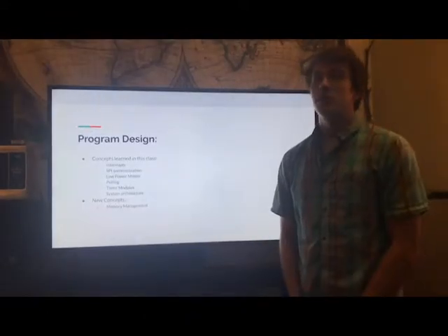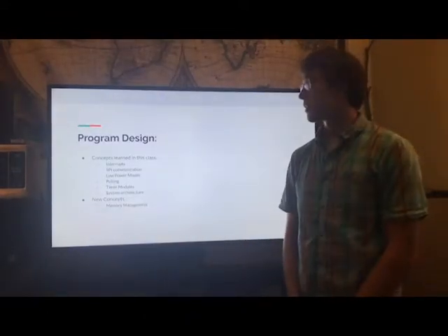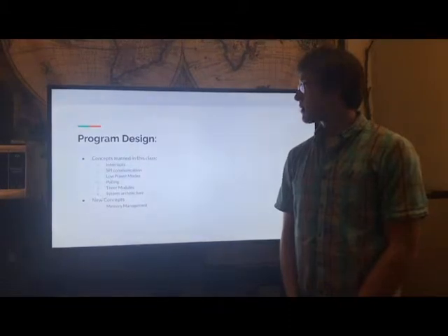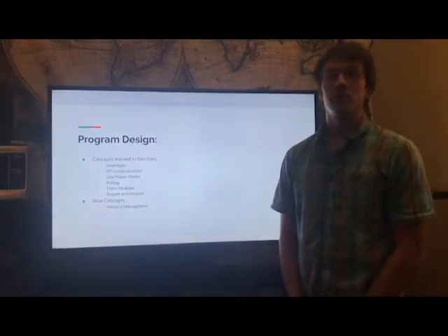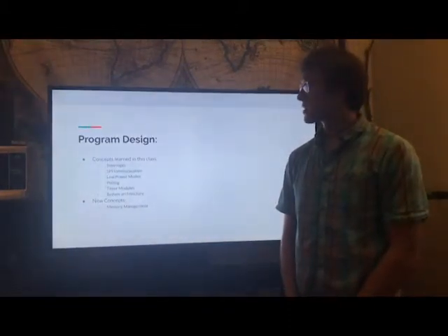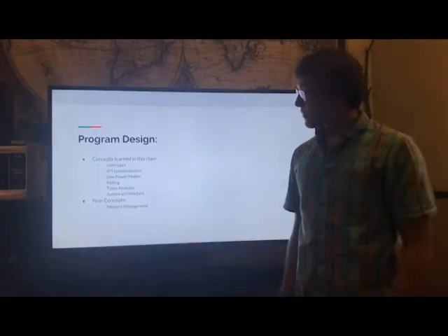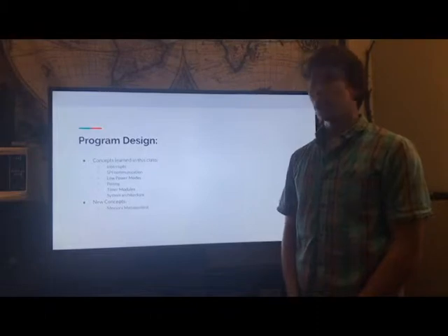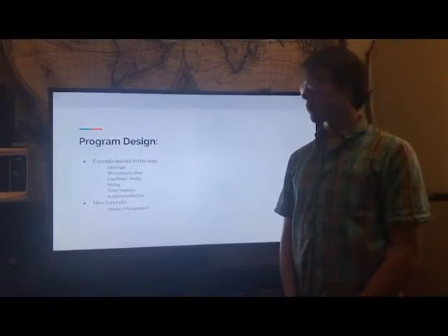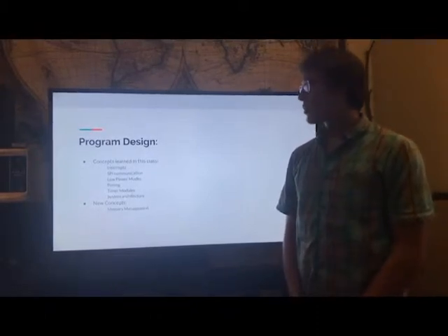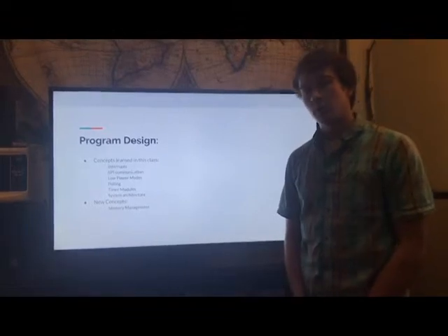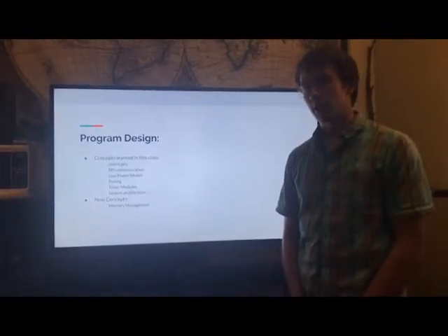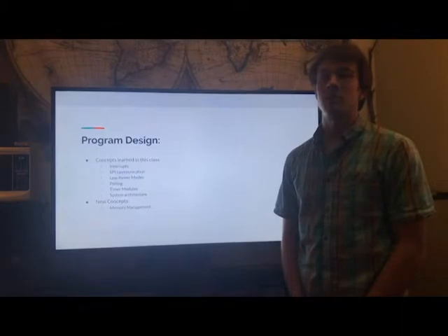This project really was an accumulation of all that we've learned so far in ELEC 327. Some of the major concepts that we used in previous labs that we were able to apply to this were interrupts, SPI communication, low power modes, polling, timer modules, overall system architecture of our program, and then one of the more important new concepts that we were exposed to in this project was more intensive memory management, and we had not been exposed to that in previous labs.